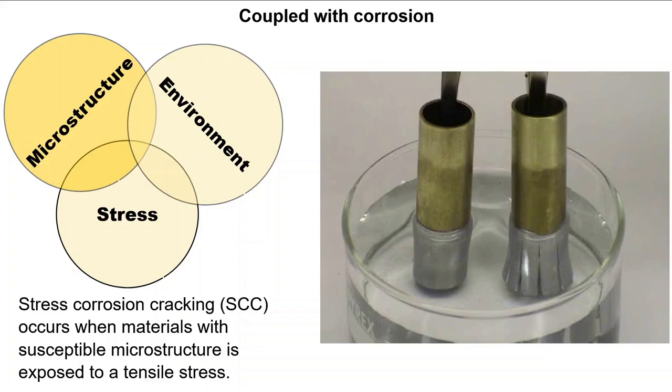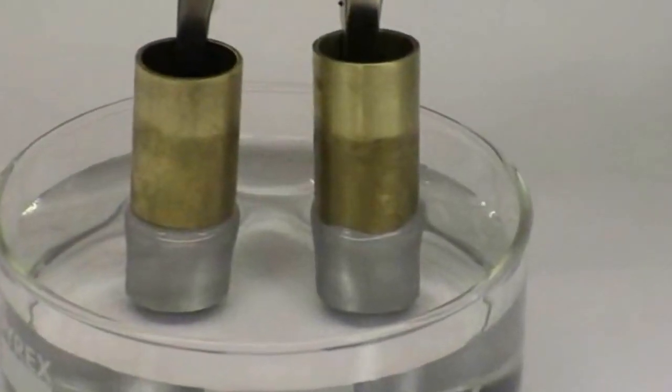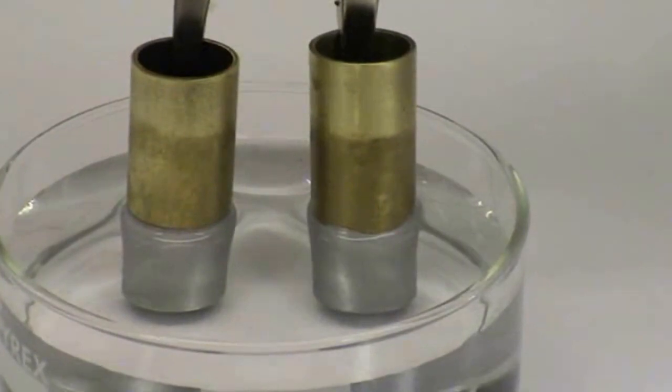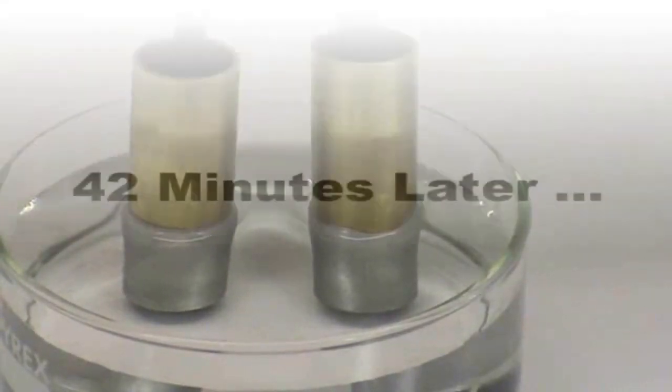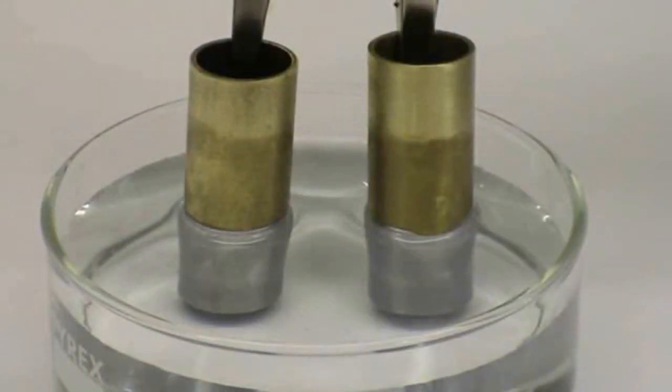To the right, I have two samples of cartridge brass, with the one on the left completely annealed so there is no residual stress, and to the right, one that is not. Let's see what happens when they're left in some mercury nitrate. Mercury immediately comes out of solution and deposits on the brass, encouraged by local anodes. The mercury then diffuses into the brass, causing significant embrittlement. After some time, axial cracks develop due to residual hoop stress. The result is fairly dramatic.